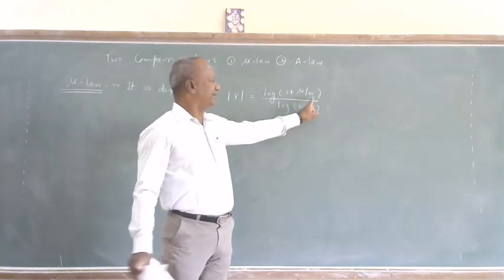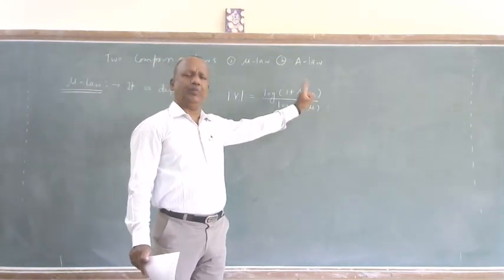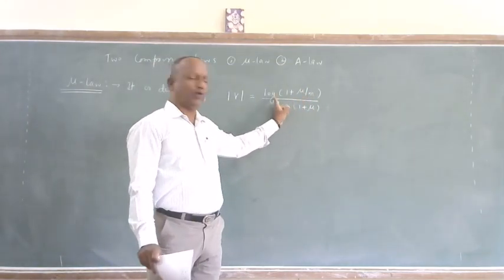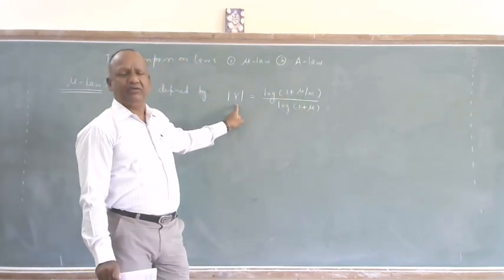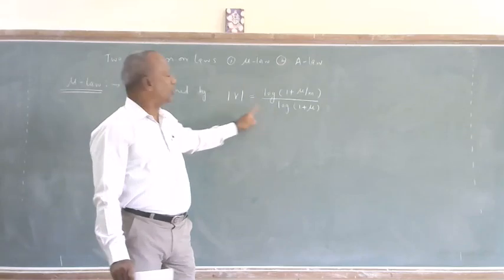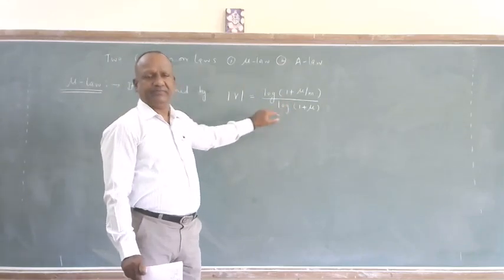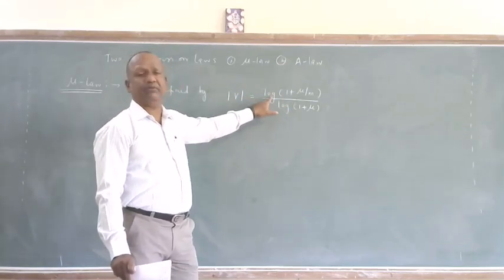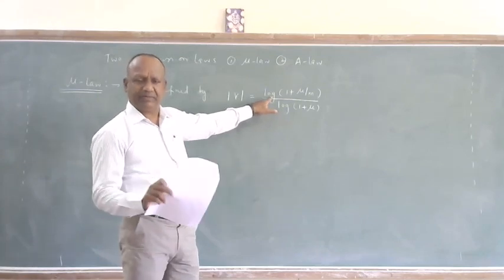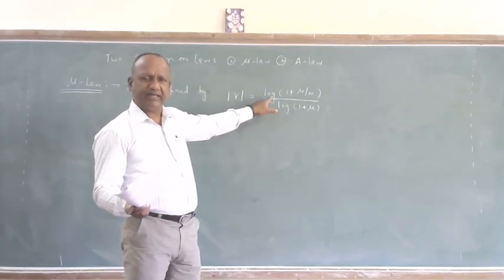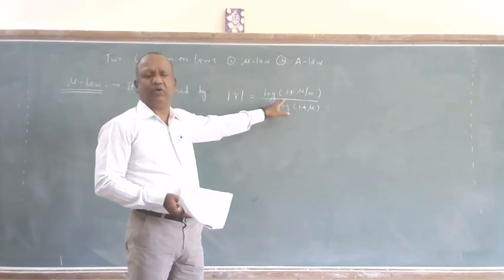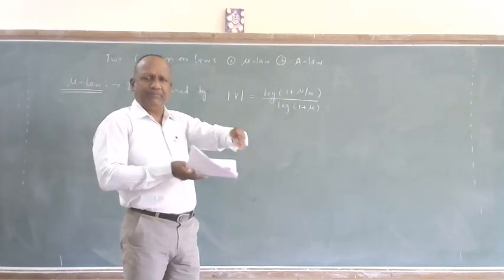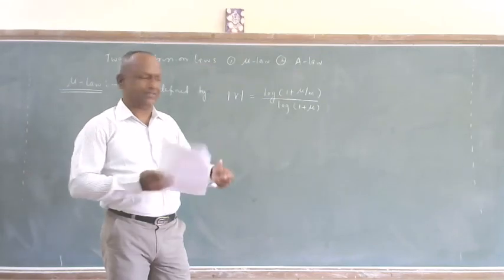M is there. I take m and operate on it in the form of a log, so that I get some output V, which does the compression of the signal. The rate of compression is in the form of a logarithmic twist. When the signal amplitude is small, it is linear. If the signal amplitude increases, the impact is logarithmic, where it is suppressed or compressed.